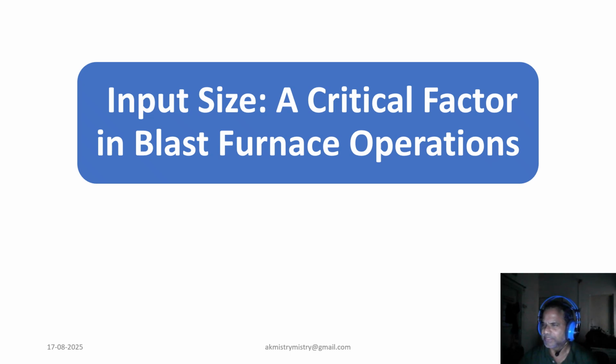Today we are focusing on a seemingly simple yet incredibly critical aspect, the size of the material charged into the blast furnace, also known as the burden input size. The size distribution of these materials is not just a detail, it's a key parameter for proper operation. It significantly impacts the particle size distribution within the furnace bed inventory and the solid concentration, which in turn directly affect crucial processes like gas flow, heat transfer, and temperature uniformity.